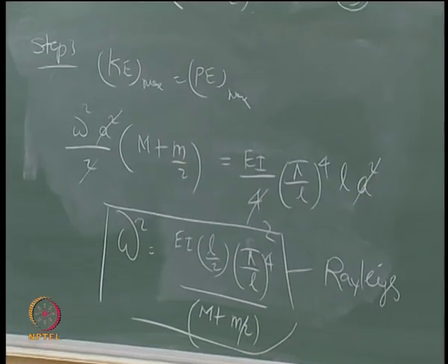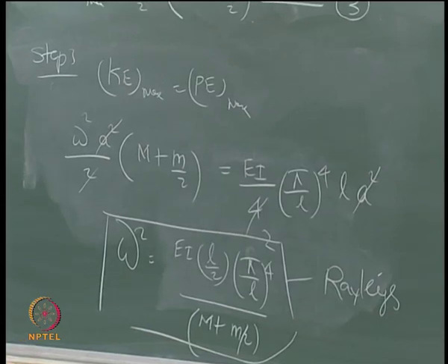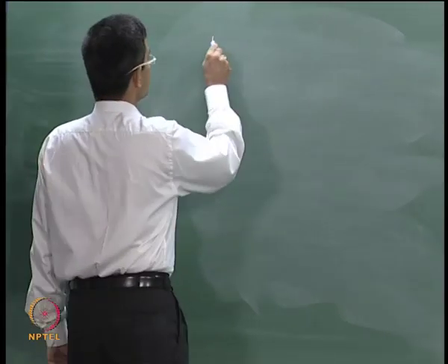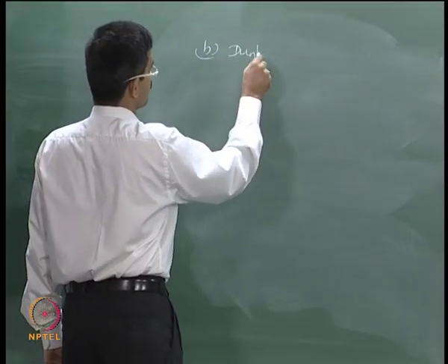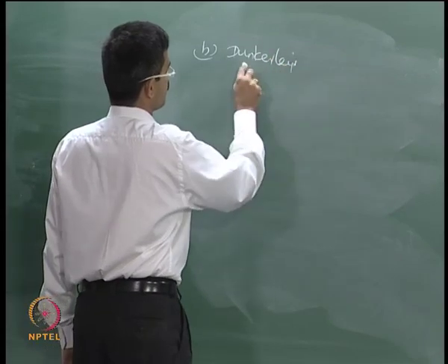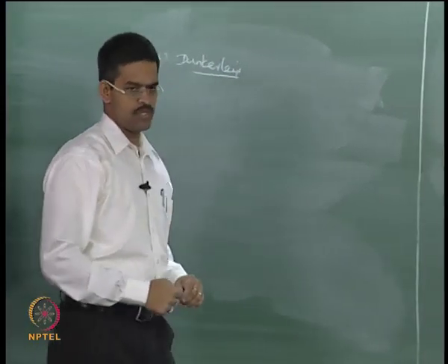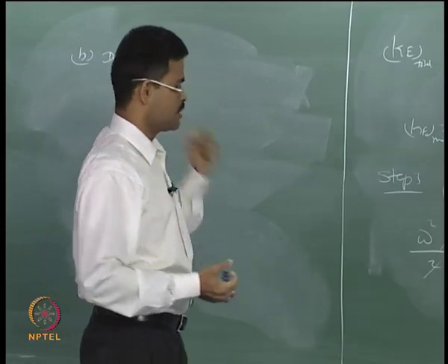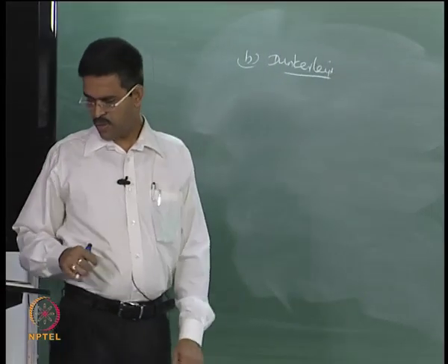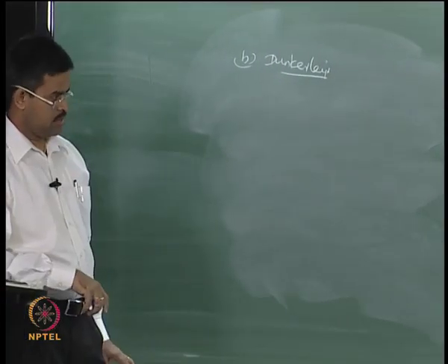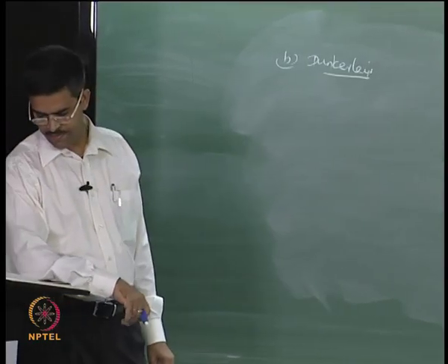So, let us see what happens in Dunkerley. Dunkerley's influence coefficients, where I should apply the unit force and get the displacements, which are called otherwise influence coefficients or flexibility coefficients.